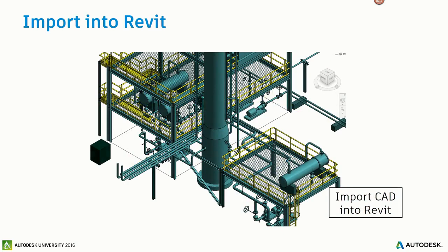So then we started doing the export to AutoCAD, and we could bring it in with import CAD and just place it right into the model, and that looked good. It showed up just fine in the canvas, but then when we started making our views within Revit, and you have to bear with me here, I'm not a Revit expert, I'm just starting to learn it, the view levels wouldn't work. It doesn't clip the geometry, in other words. So you go in to do an elevation on level 2, and then you see all this pipe and equipment sticking through there, and it's like, okay, that won't work. So that's when we got into using the part family import.